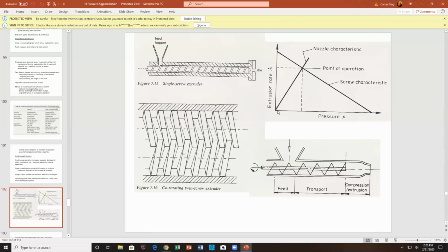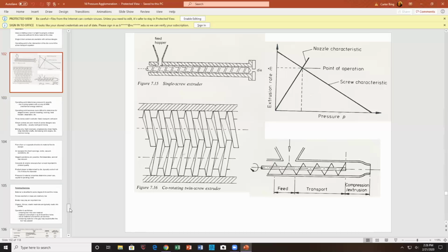And the nozzle characteristic you need to get a hold of as well. That represents the pumping system that you're pumping through. So this is a complete analogy to the mechanical energy balance, pump curve, and standard undergraduate fluid mechanics, which is rather sparsely covered.